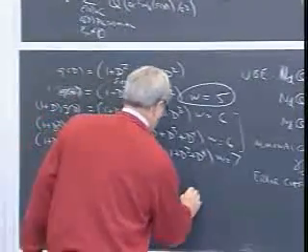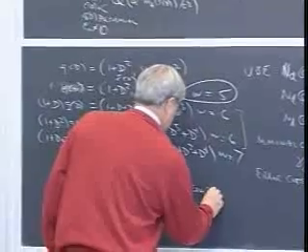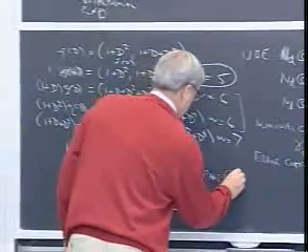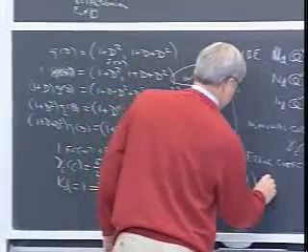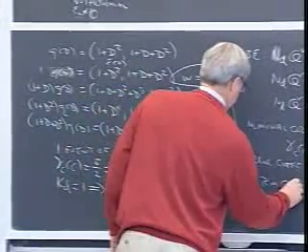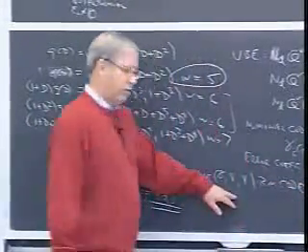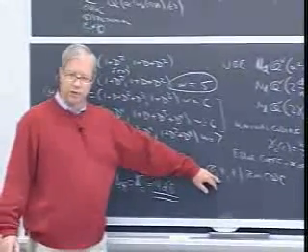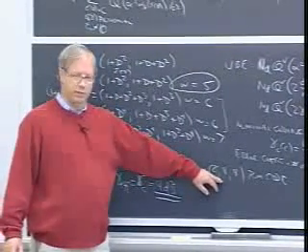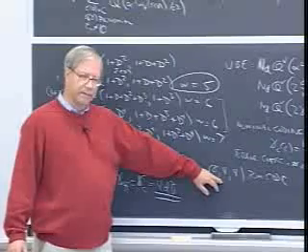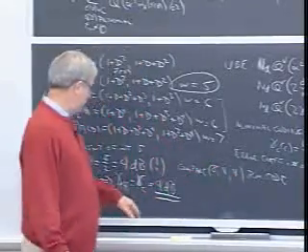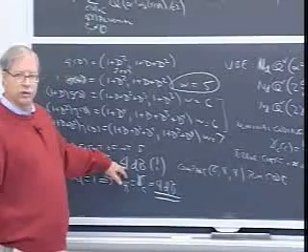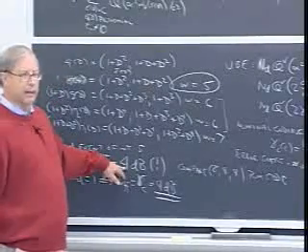This code compares very directly with the 8-4-4 Reed-Muller code, block code. This code also has rate 1/2, it has the same rate. We'll see that it also has a 4-state trellis diagram. But it only has distance 4, which means its nominal coding gain is only 3 dB.